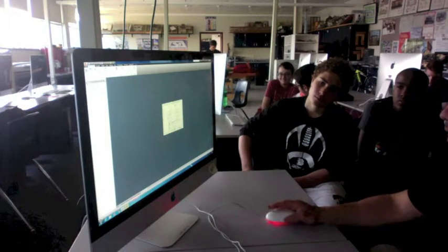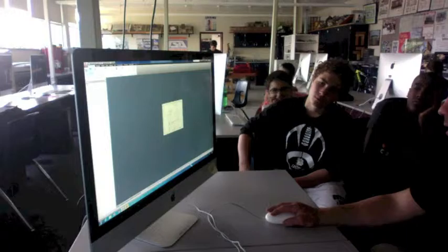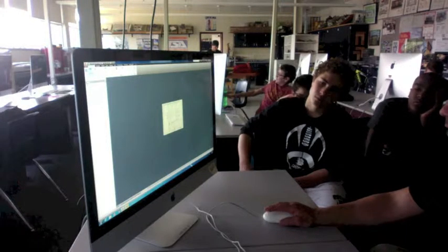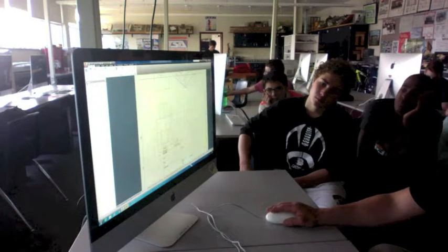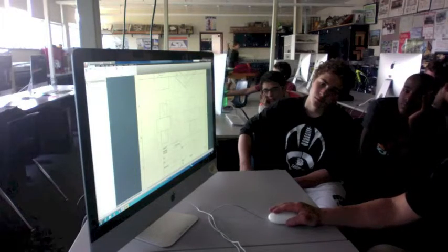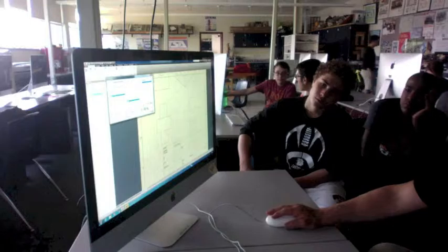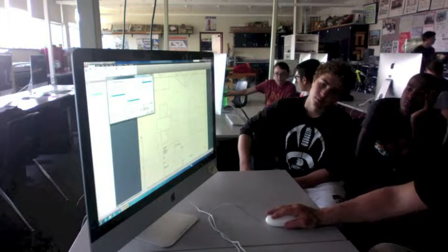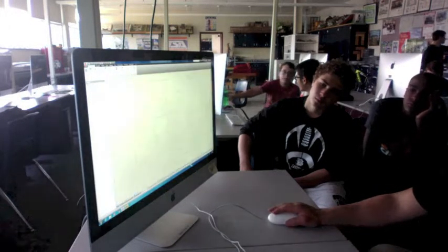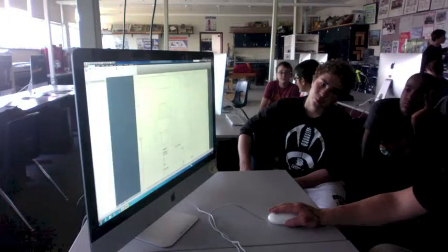Oh, the top didn't get projected, so I can go to projected, pick the base view, and drag up and create that view. Now, you don't see any hidden lines either, so I'm going to double click. I'm going to pick this style under hidden lines. So you can see those hidden lines through my part now.